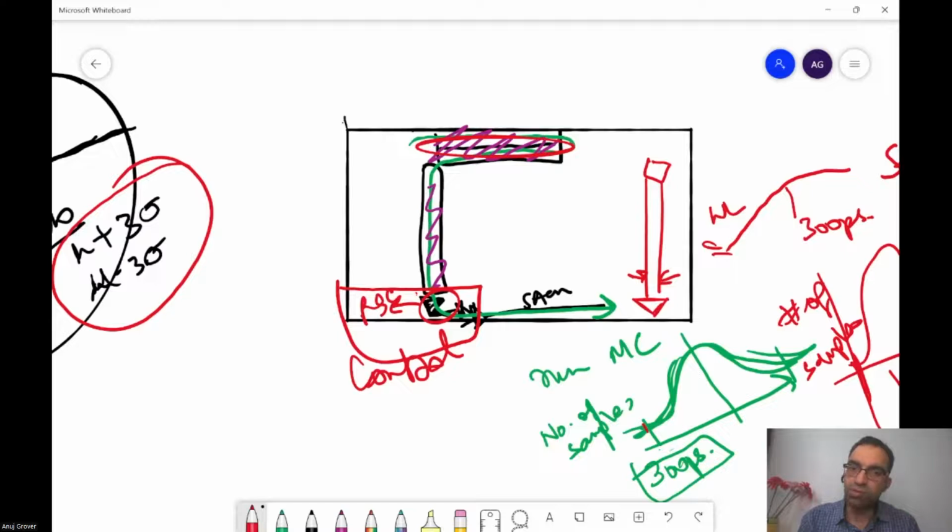Yes sir. To generate the reset, you saw two horizontal signal delays. And until you reset the word line, can you start to precharge the bit lines? No. Right? Yes sir. So you reset so that word lines can get deselected and you can start to precharge the bit lines as soon as SAEN comes. Okay.